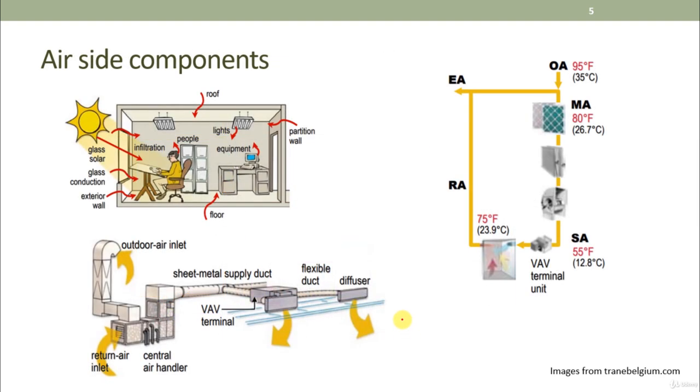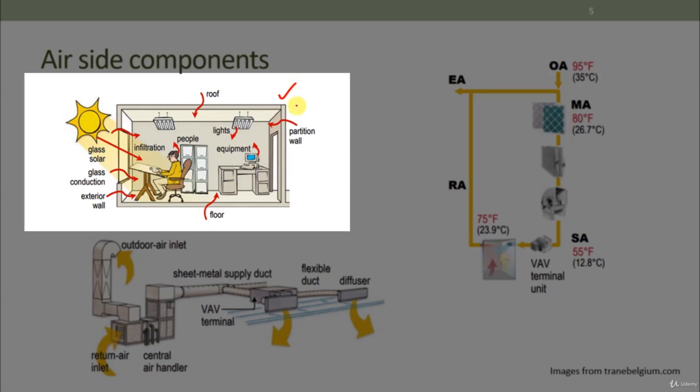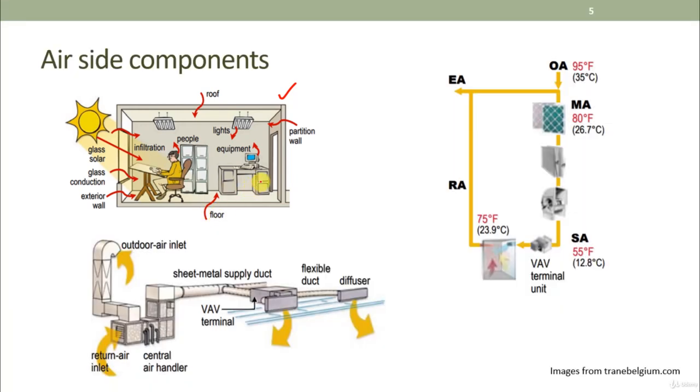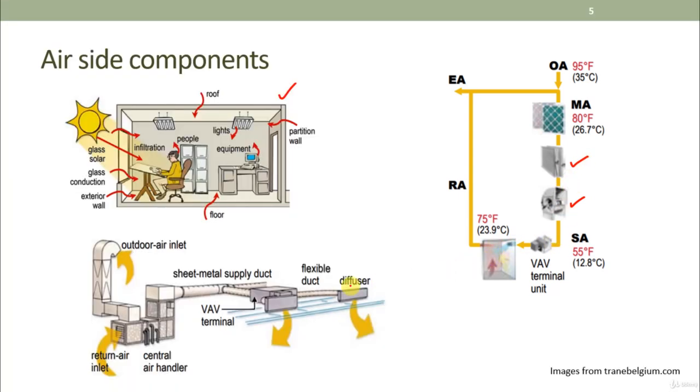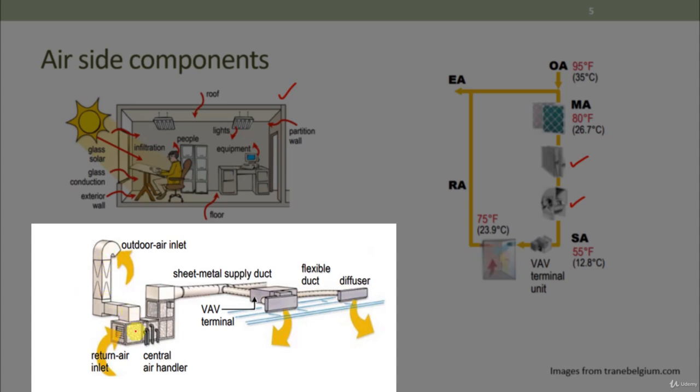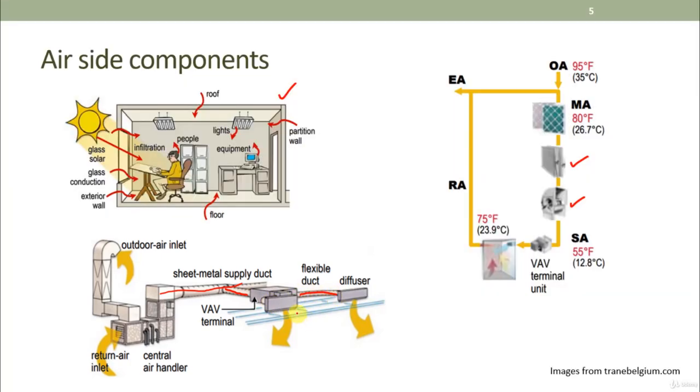In this course, I will start off with the calculation of space cooling load, identifying different internal and external heat gain into a space, as that is the starting point or motivation behind the equipment selection downstream. Only when we know the cooling load is it possible to size the equipment such as a supply air fan and the cooling coil to ensure that they can deliver adequate cooling to the space. The transportation of air is through air ducts, and this is critical too. So you will learn how to determine the correct duct size for different requirements and applications.